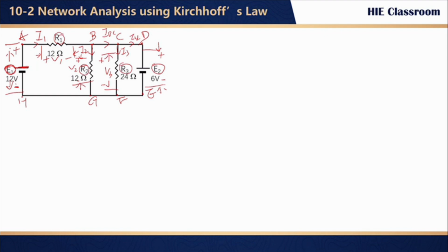Easy so far, right? With current and voltage labeled, let's write some equations using Kirchhoff's laws. First up, the voltage law. It says all the voltages in a closed loop add up to 0. So let's find a loop. Start at A, go through B, J, and back to H. That's the A, B, J, H loop.